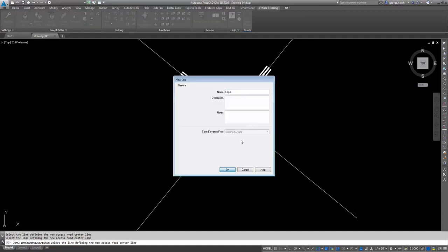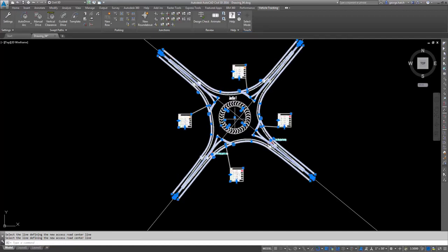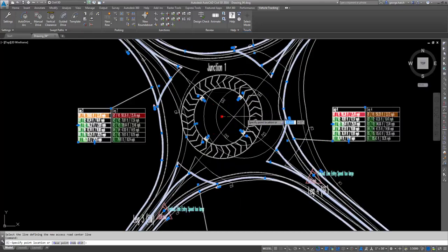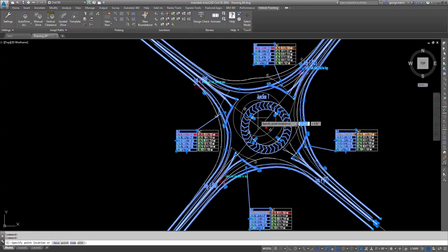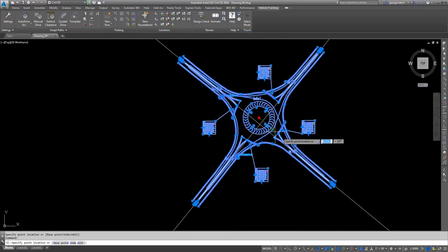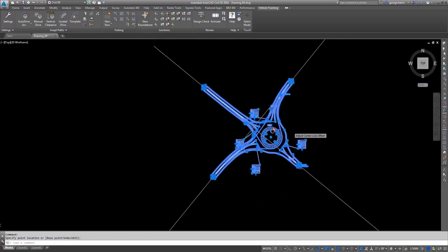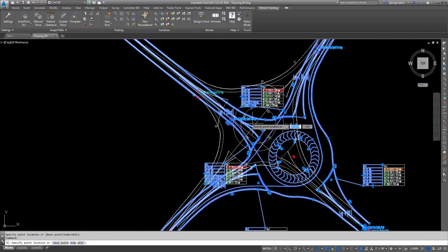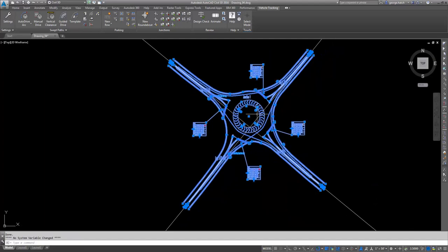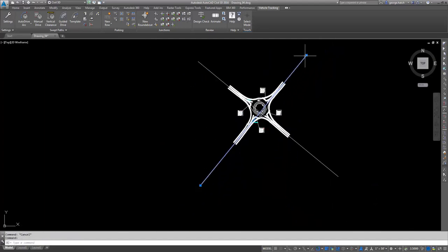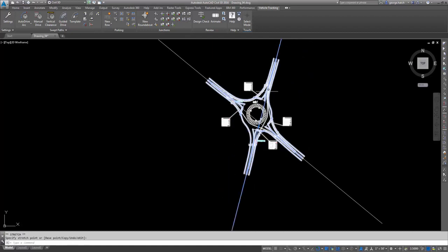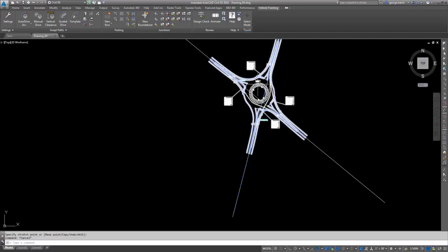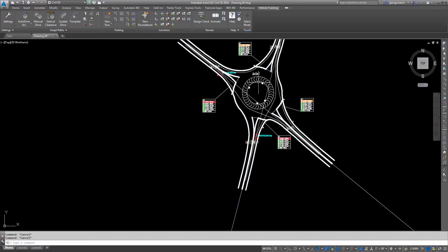And you can see, if you've done this before, you're already noticing that this is much faster than any other solution that you probably tried in the past. And it's dynamic, meaning that I can change the location, the center line maybe of this roundabout, and it will automatically still read the center of those polylines that I lay out. Now they're polylines. Remember, they are not Civil 3D alignments. They're just simple polylines. And yet the roundabout tools are intelligent even to those polylines.